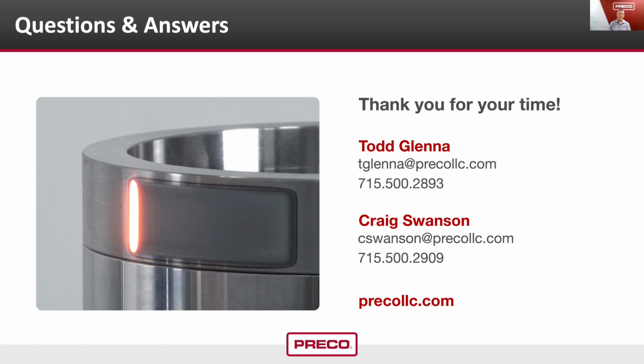As Todd mentioned, with our applications development group and our engineering groups, we can look at those prints and assess if we need a special head, or if we're able to come in at an angle of incidence to get the effective heat treat needed. It does not have to always be normal with the part. We can come in at an angle.